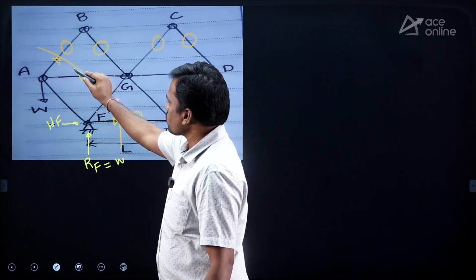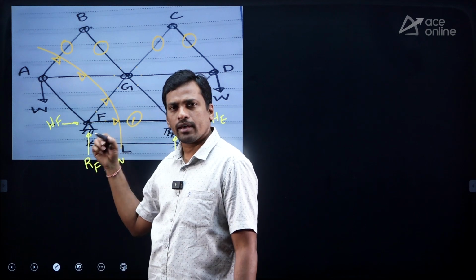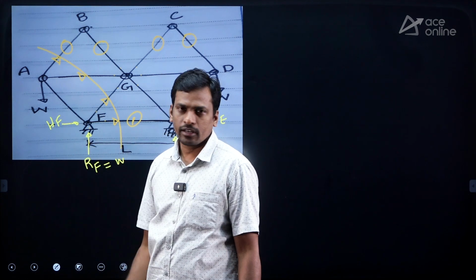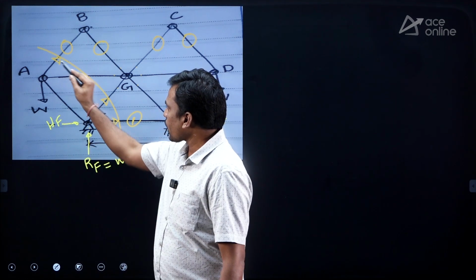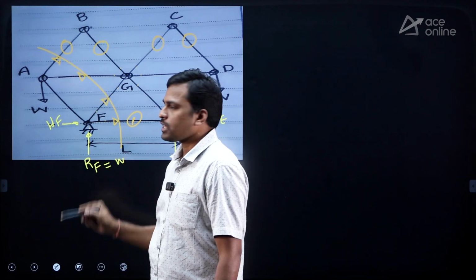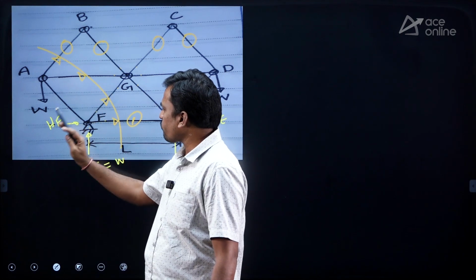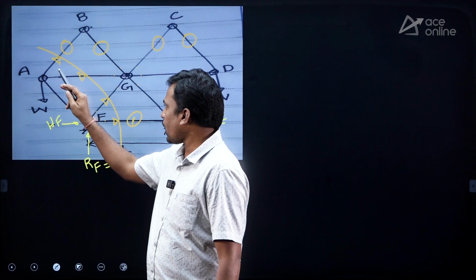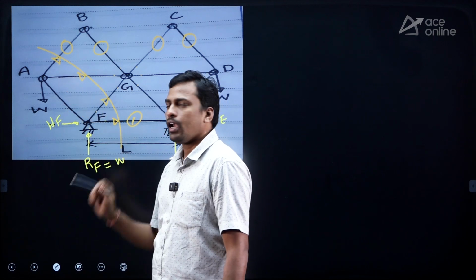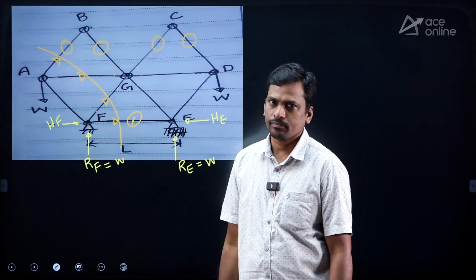And you can assume compressive force also. I told you, you can assume always either compression or tension. Only for cut members do we have to assume tensile force. I am just balancing the left part of the structure. This is the reason I assume tensile force only for left part members.